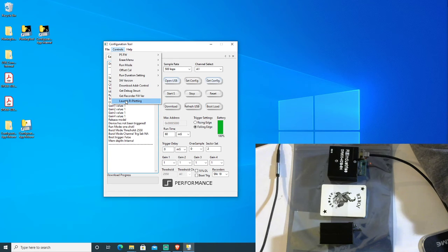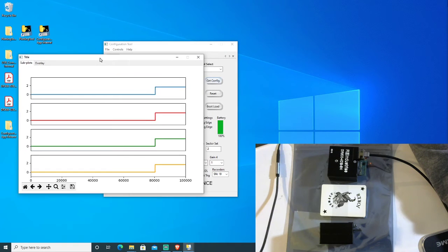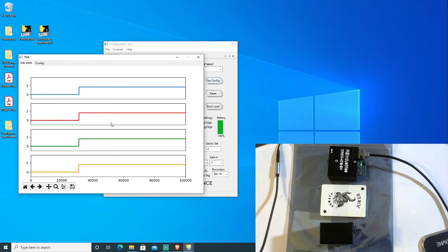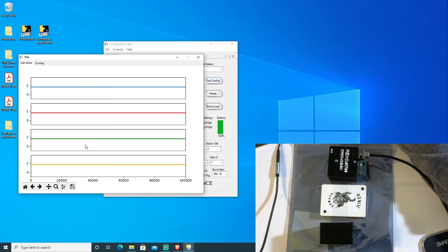So this is real-time plotting capability here. This data recorder is actually plugged into 3 sensors and 1 signal generator, and we'll just use a signal generator as an example. It's on channel 3, so we have channel 1 at the bottom, channel 2, channel 3, and channel 4. So we'll just inject a sine wave into channel 3, but this is a 3,900 sample per second per channel heads-up display real-time here.